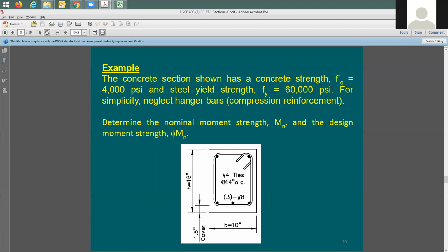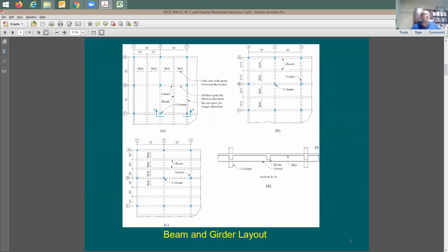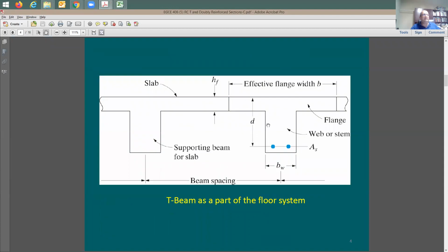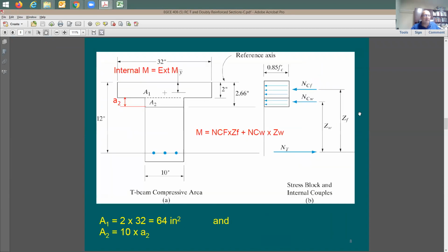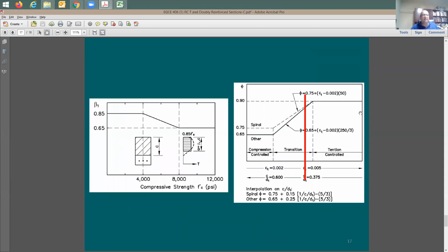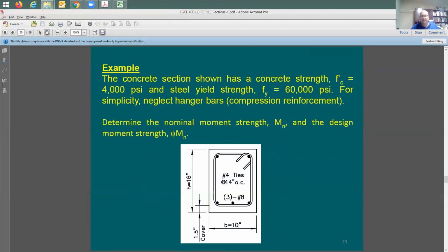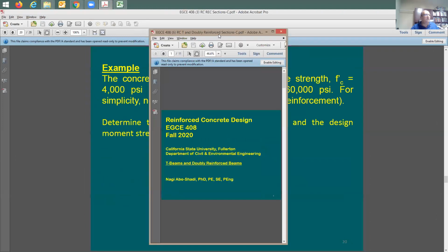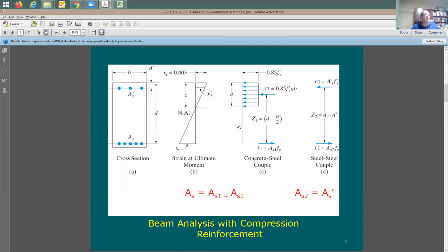Yeah, I remember that. Second step, T-section. We said, okay, here's a T-section and just some tension reinforcing. Third step, we start to consider the compression reinforcing that we have already there, but usually we are ignoring it. So that was all about the T-sections, right? And then we start to make it more complex. We start to put the compression reinforcing in our analysis.